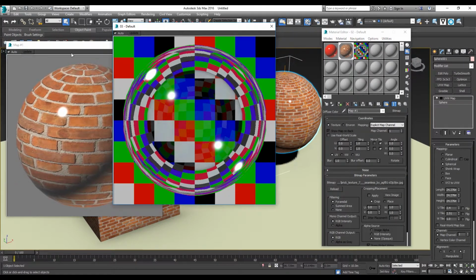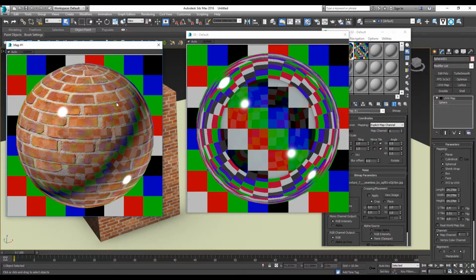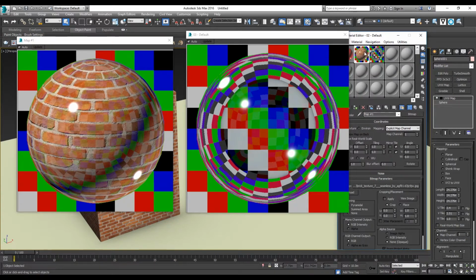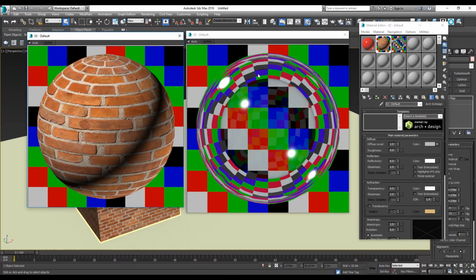So for example, this is the brick and this is the glass where you can see through the background. As you can see, there's some reflection on the brick, which we can simply lower by adjusting the reflectivity to 0, because bricks normally don't have a reflection, whereas glass you want it to have a reflectivity, which is preset in the template.